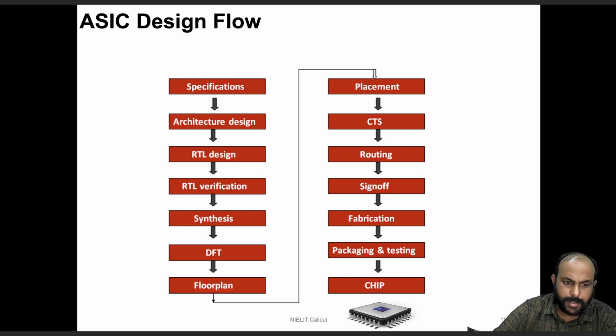Once RTL design is done, it is subjected to a variety of functional simulations wherein the design engineer himself or herself will be looking for possible bugs or compilation errors, and those will be resolved at that stage. Once the design engineer is satisfied about the conformity of the design or the description to the specification, he will push it to another team called RTL verification engineers.